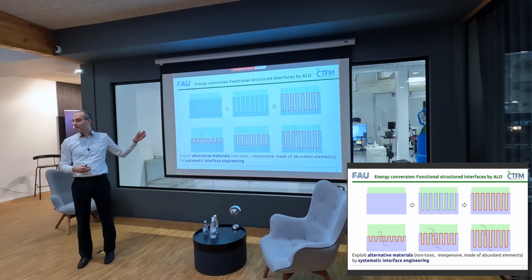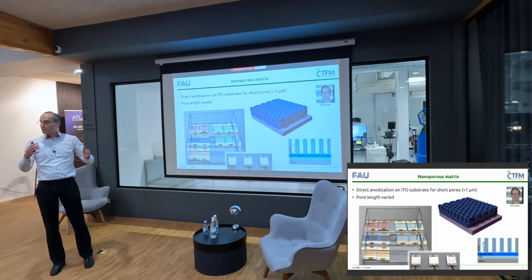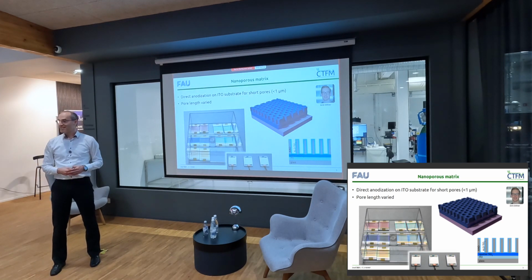And of course, there we will work with porous materials. And if we do, then ALD will be the method of choice to provide the functional material, the red line here in my sketch. And so to start with, typically we make pores, and we've already heard about those pores yesterday. We make them by anodization. If we are to make something that is electrochemically active or photovoltaics, then the electrical contact on one extremity of those pores will be very important.